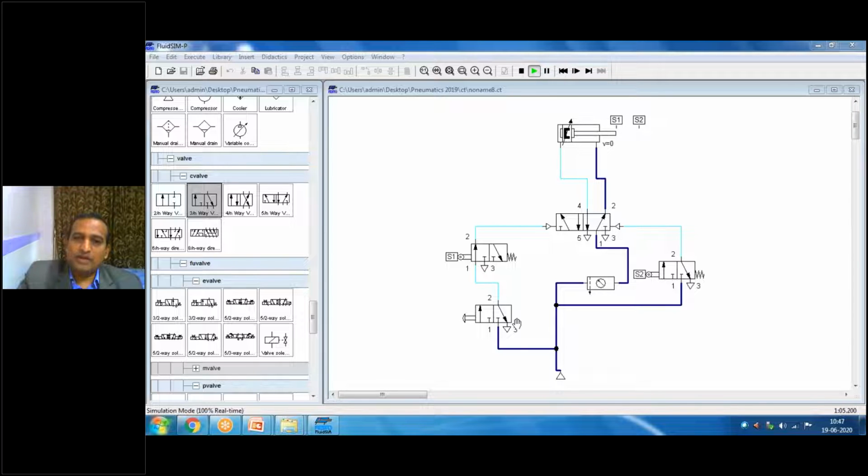And here also you can go for an AND gate. Especially, I have told a good example is a press machine. 2 buttons you are applying, and only if you press both the buttons, then the ram will come down. So OR button, OR gate, OR logic, you can use any type of logic in pneumatics, but it is tougher, and only 20% of the industry are using it, like paint industry, chocolate industry, chemical industries. But the other 80% of industry are using electro-pneumatics and PLC based systems.